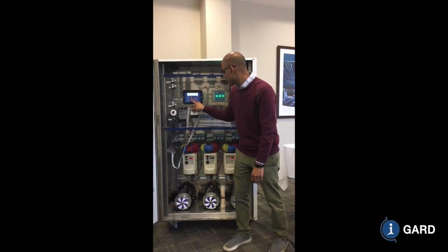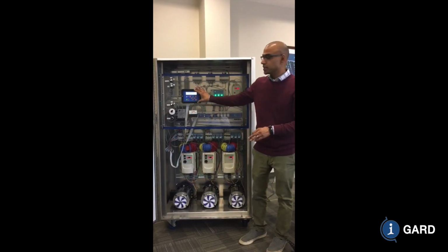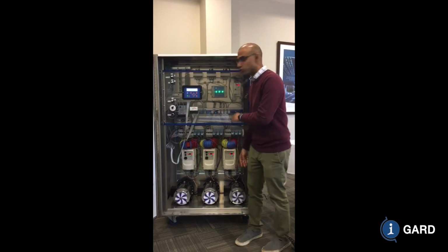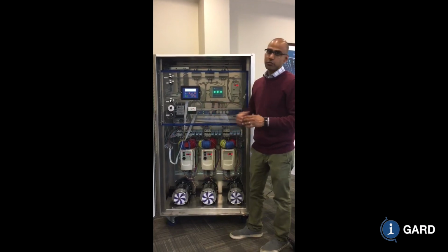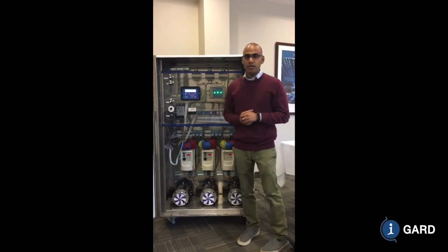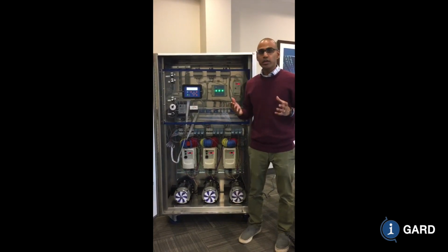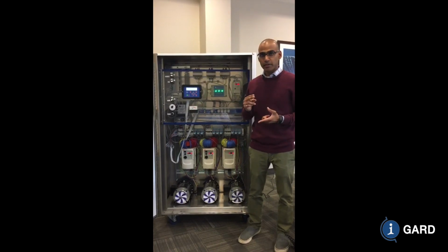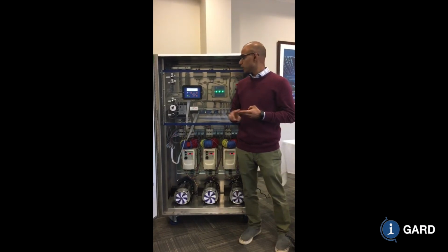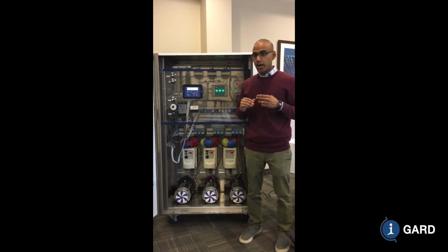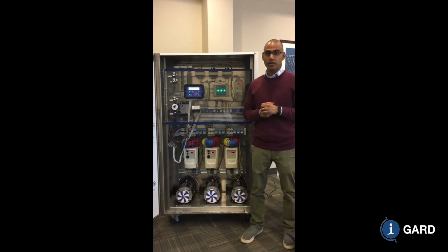So I press reset and bring feeder 2 back on. Note that you have to reset the DSP before resetting the breaker. The trip signal that is sent to the feeder remains on as long as that feeder is tripped. So that's just a basic overview of the DSP system and how it functions, what you can expect to see in terms of finding a first fault and using pulsing as a method of fault location, navigating the screens, and looking at how a second fault occurs and what you see when a second fault occurs.